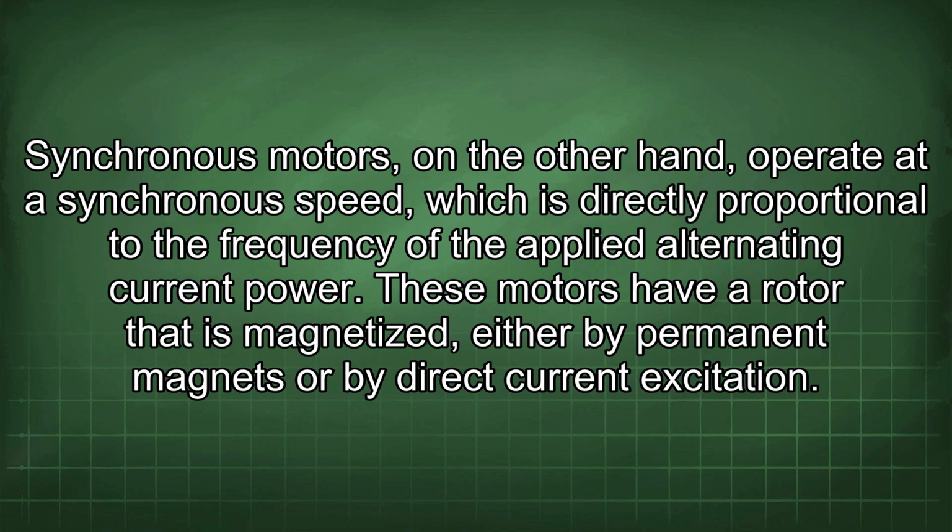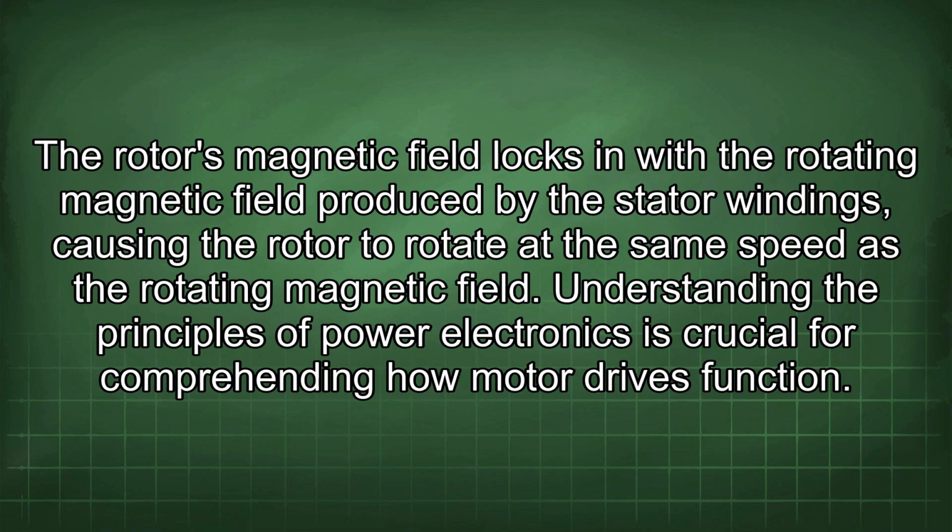Synchronous motors, on the other hand, operate at a synchronous speed, which is directly proportional to the frequency of the applied alternating current power. These motors have a rotor that is magnetized, either by permanent magnets or by direct current excitation. The rotor's magnetic field locks in with the rotating magnetic field produced by the stator windings, causing the rotor to rotate at the same speed as the rotating magnetic field.